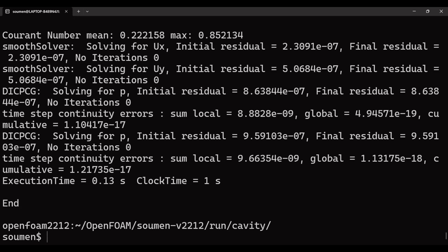Now let me try to open paraFoam if it works. The paraFoam command is to call the post-processing unit, which is ParaView in this case, from the OpenFOAM environment itself. But sometimes it may load an older version of ParaView. If you want to load the recent version you have installed, the best way is to create a file using touch.